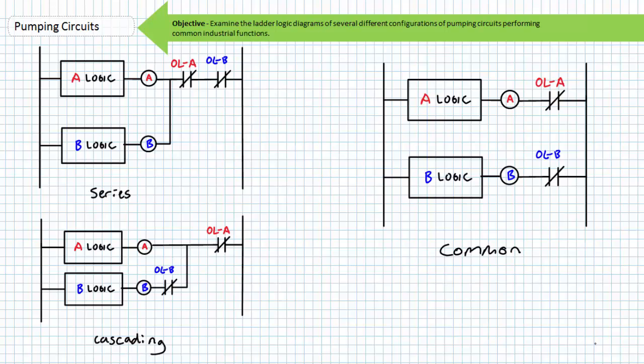Related to this topic, note that overload relays, especially older ones, sometimes feature not one auxiliary contact, but rather 3 auxiliary contacts, one for each phase. For very important reasons, a motor starter making use of this type of overload relay must use all auxiliary overload contacts in series with one another. This way, if one or more phases are in overload, the condition is recognized and the motor de-energized. Rather than drawing this schematically as 3 separate overload auxiliary contacts in series with one another, sometimes you'll see one overload contact with words "all overloads above it."